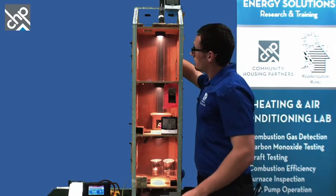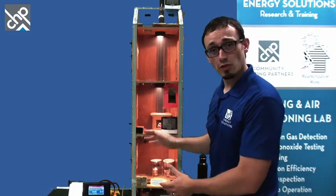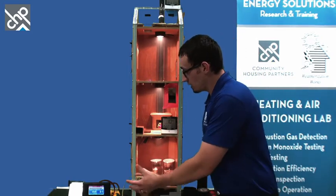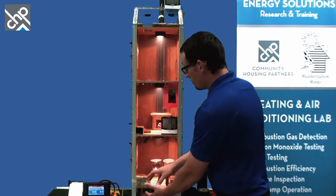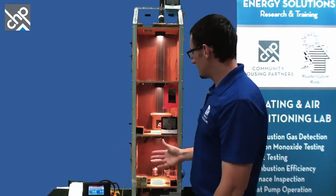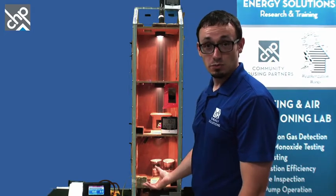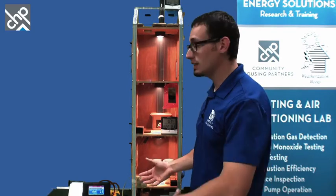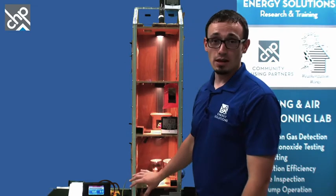So if we've got that airflow, we've got leakage in the top of the building, we've got leakage in the bottom of the building, and that air is flowing from the outside into these other regions, and then moving on into our house. Simply what that means is that we're going to be breathing in this condition when it's warmer inside the house than it is outside the house. We're going to be breathing whatever air that's bringing in. That is convection. We are losing heat because that tendency for that heated air to rise up and out, and then it's drawing in whatever makeup air it can.